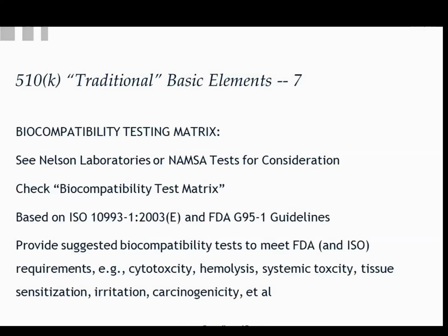What I've done, and I've done this for years, is I include not only failure modes on the left-hand column, but normal use problems, like anaphylactic shock, allergy reactions, and things like that. So that addresses the concern that some consultants have stated that FMEA or FMECA is not an effective tool for medical product risk analysis. I would disagree.